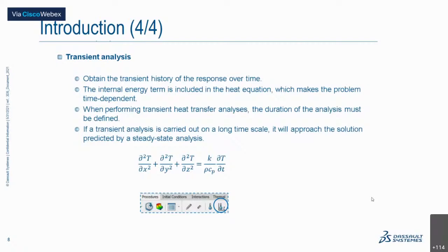And the transient analysis, if you do it for a long span of time, the results are similar to that of a steady state heat transfer analysis itself. And the options or the commands that you'll be using in order to have these simulations generated are the ones in the last graphic that are shown there. So if you use the first option there, it will help you in generating a steady state heat transfer analysis step. If you use the second one, it will help you in generating a transient heat transfer analysis step.